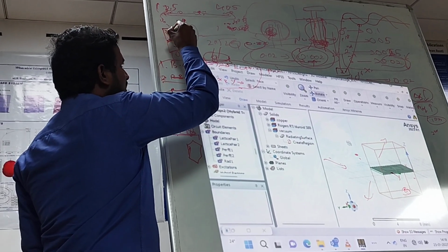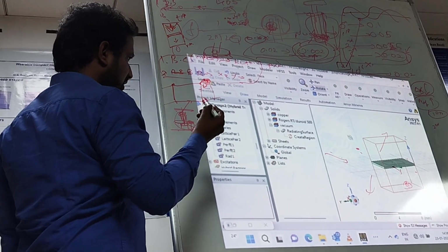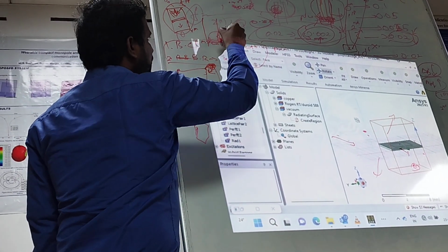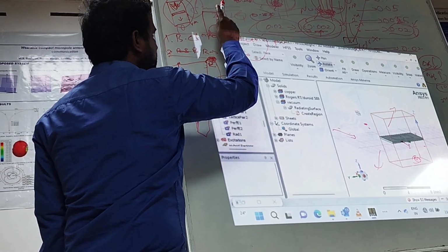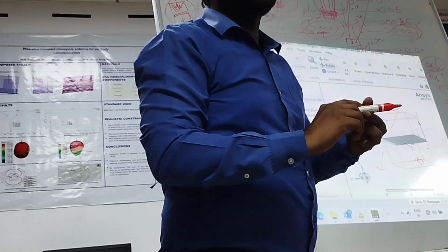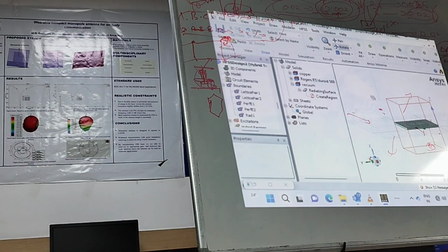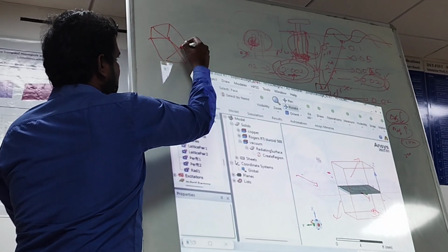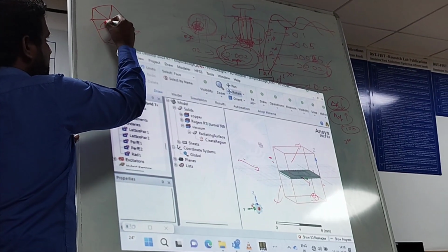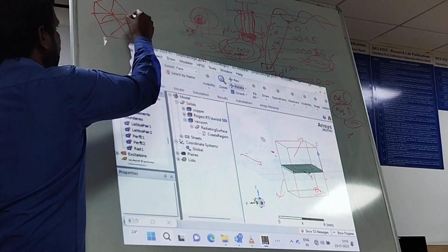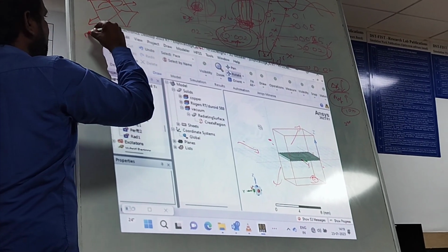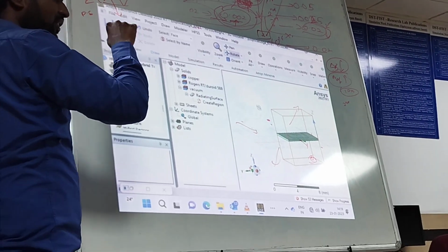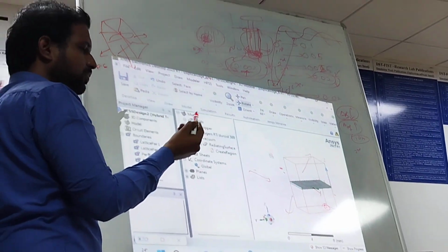In a plane wave excitation, we can define this unit cell analysis in another way also. Let's suppose this is a box kind of structure which we are making and this is the element which we are keeping in between. So the two opposite faces will be perfect E, and one will be master. Before master and slave, also without using the Floquet port, if you want to go with a wave port or lumped port,